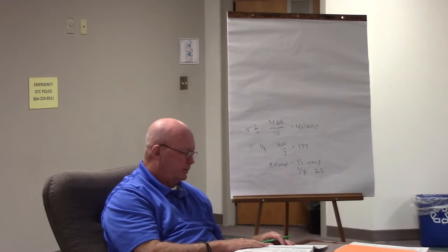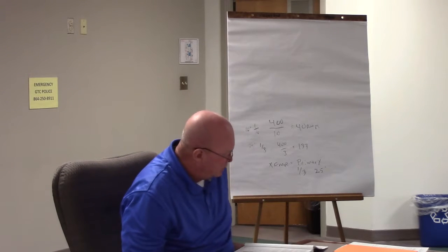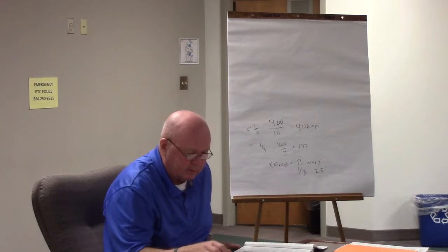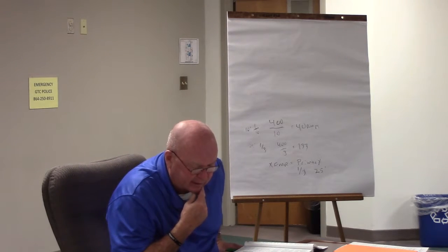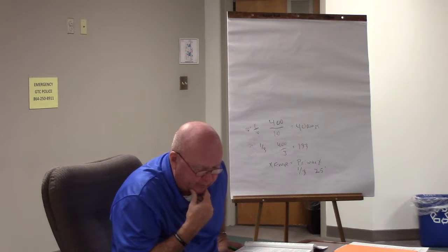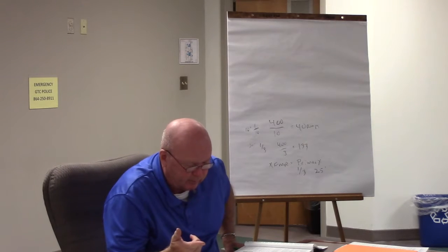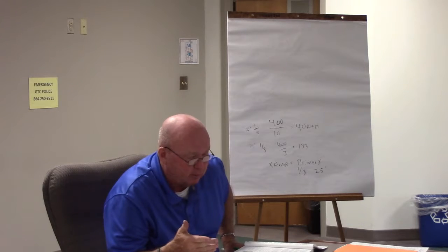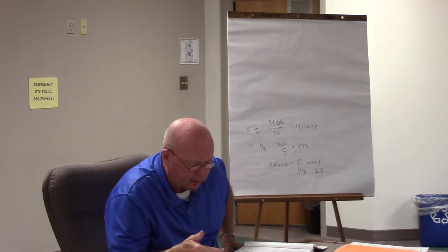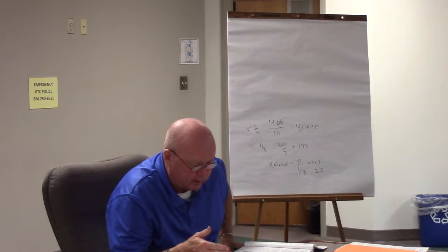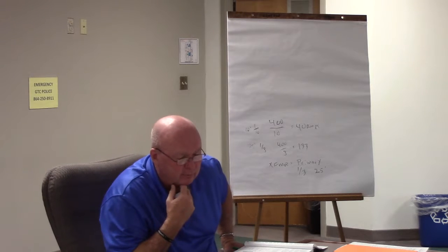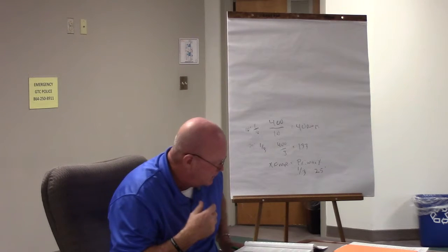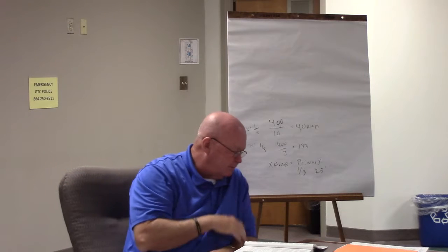100-foot tap rule. 240.21(b)(4). Okay? B4 taps over, as a matter of fact, it says taps over 25 foot. But if you look at number 2 under that in the code book, the tap conductors are not over 25 foot long horizontally and not over 100-foot total length. That's where they're getting that from. So there are some rules governing that.